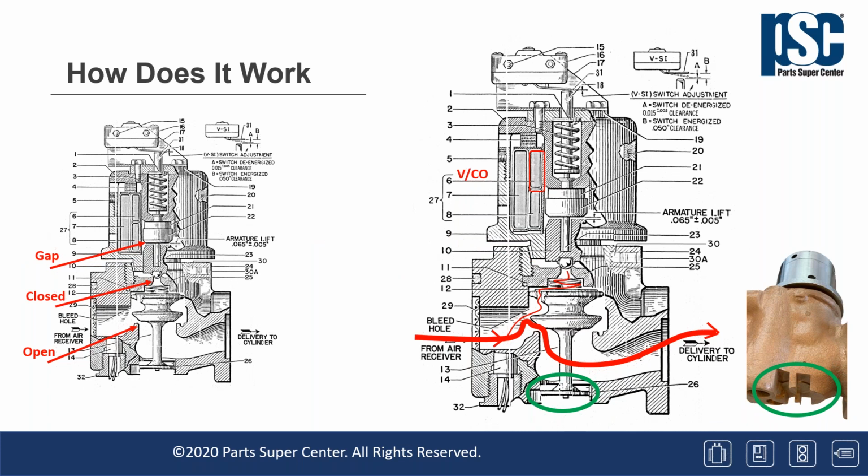The auxiliary switch contact or mechanism operated contact has interrupted the current to this VC close winding, and another auxiliary switch or contact or mechanism operated contact has now energized the cutoff winding, VCO.